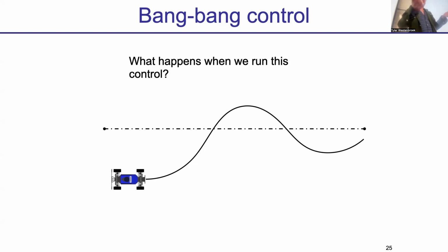Oh, again, it's going to flip, which is a more extreme version of what I was going to say, which is your car is going to start vibrating, it's going to start shaking, it's going to start tilting. And again, we design our controllers with these very simple models. Generally, as you start to shake your control systems more, these shakings introduce new, more complicated dynamics, which make your model even more wrong. And so a guiding principle for a lot of control is you want your control to be as smooth and as nice as possible, because this stops your system from just going crazy.